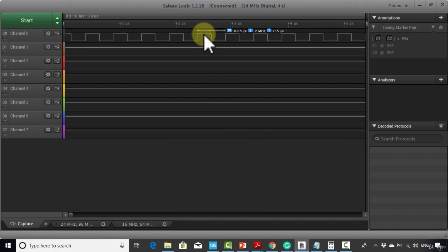That's great. So we successfully switched the system clock from HSI to HSE, right? So now the system clock is running with 8 megahertz. That means your processor is also running with 8 megahertz of clock.